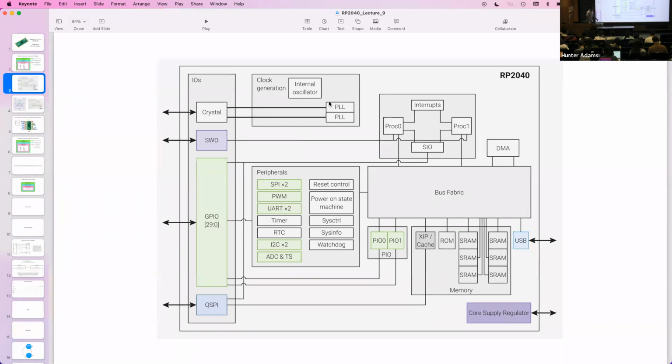So in the cache, we're storing the code that's running for fast execution. If we hit an interrupt and the code that interrupt runs hasn't been cached here locally, we have to go get it from the external flash. That can take some time. And there is actually a compiler directive where you can tag a particular bit of code and say, I would like to please store this in cache. And that mitigates that problem. But it's an interesting thing that you might observe if you start timing your interrupt service routines.